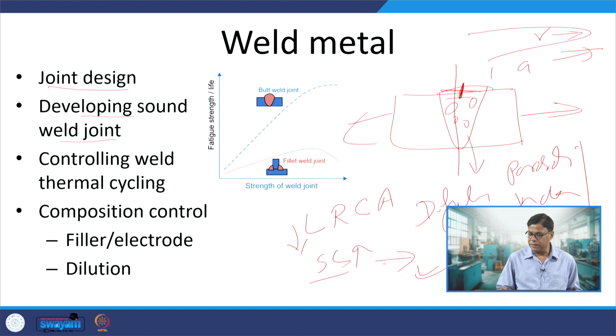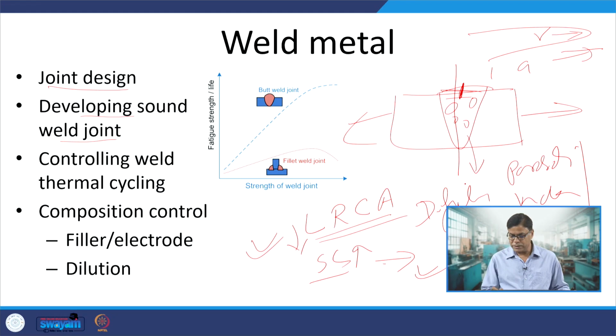Therefore, it is important that the defects are eliminated. When the defects are eliminated using suitable approaches, that will avoid the situation of reduction in load resisting cross sectional area, and it will also avoid the stress concentration due to the presence of the defect.